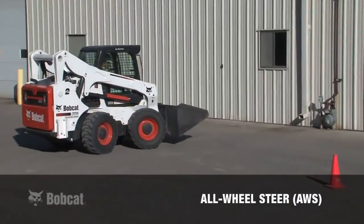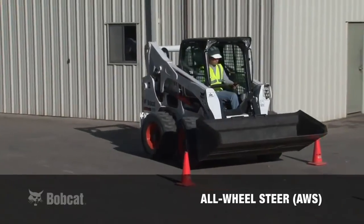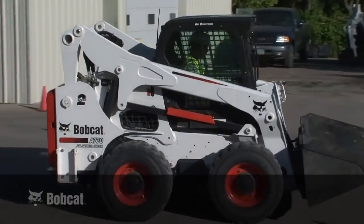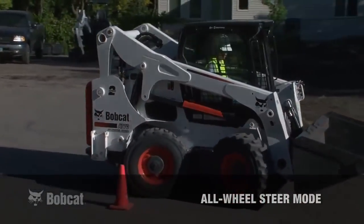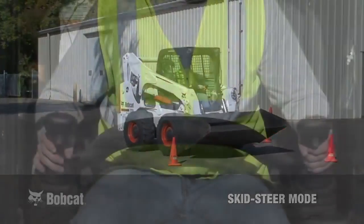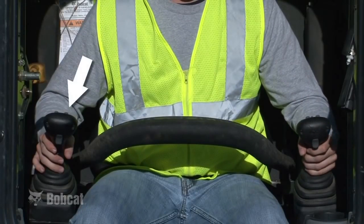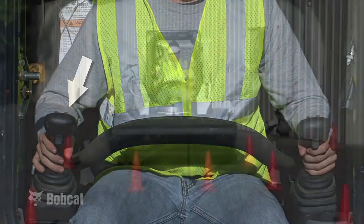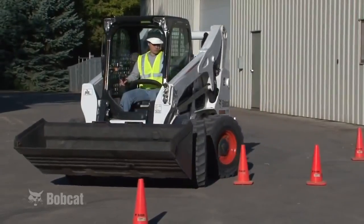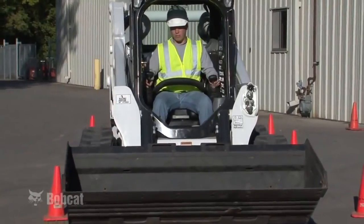The Bobcat all-wheel steer, or AWS loaders, also provide joysticks to control drive, steering, lift and tilt functions. The operator can select between 2 different steering modes, the all-wheel steer and the skid steer mode. Regardless of the steering mode selected, the left joystick controls drive and steering functions, while the right joystick controls lift and tilt functions. When in AWS mode, you get precise steering from the coordinated action of all 4 wheels. If high range speed is selected, only the front wheels provide steering.